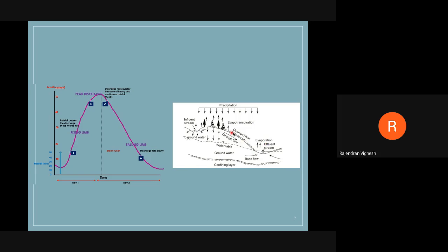When the runoff is very heavy, the nearby river and streams will get full. The storage capacity of that particular water body will be full. After that, it will come out as flood or overflow, so that becomes a danger. That's why we are studying hydrographs. The basic necessity of studying the general hydrograph is to see how the river is affected by a storm or any rainfall, how rainfall affects a water body when the surface runoff is very high.